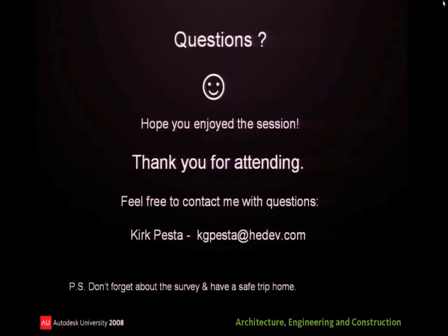Okay, the question is, explain a little more about our custom VAV box family. We have a lookup table that, based on the flow that's connected to that box, the size will change. So in the lookup table, we have values for the airflow, and those values will be associated with the inlet size, the outlet size, and the physical size of the box.